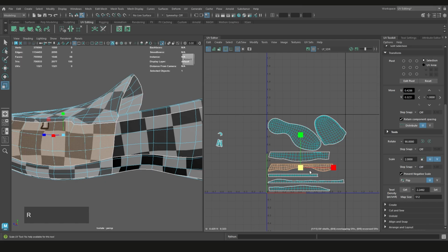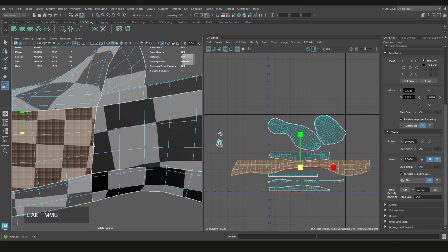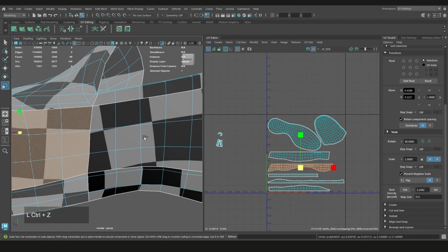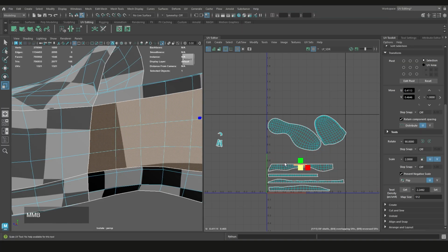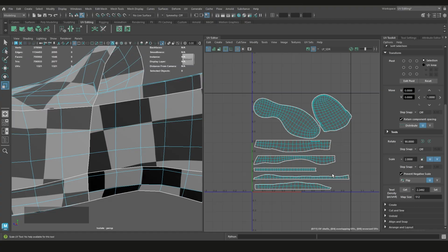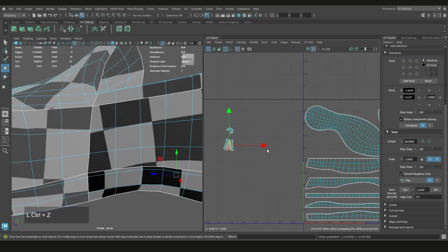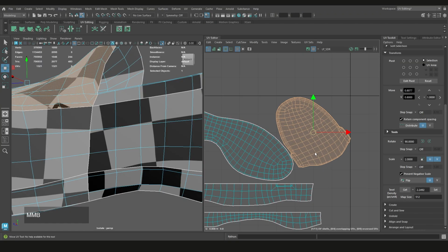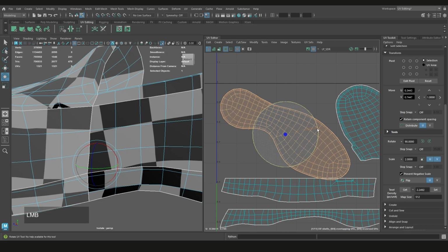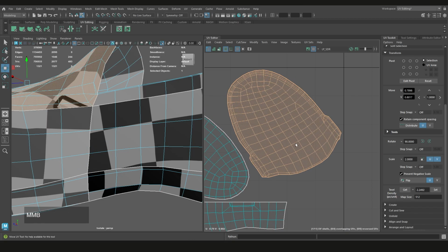Why? Because if this one is too big, when we texture it, right, this is going to look really crisp, and then all of a sudden when you come here, it's going to be kind of blurry, right? Because we made this bigger, so it's taking up more texture space, and we made this one smaller, now it's taking up less texture space, and that's going to be a bit of a problem. If you don't understand what I'm talking about, we will cover that as we go, right? So I'm going to move this one right over there. Actually, before I do that, let's sort this out. So again, they can't be touching or overlapping, and they can't be touching or overlapping there. So there we go there. Yeah, okay, so we managed to put that in.